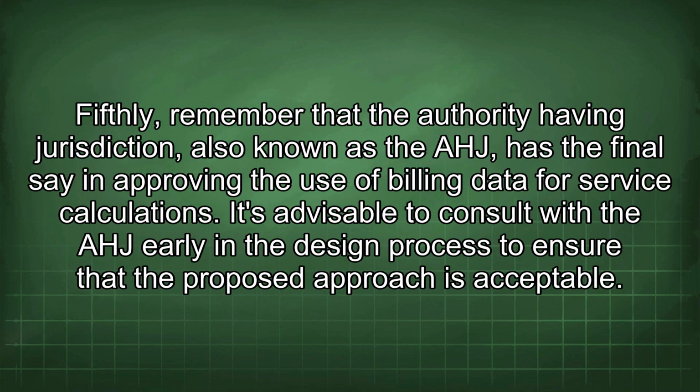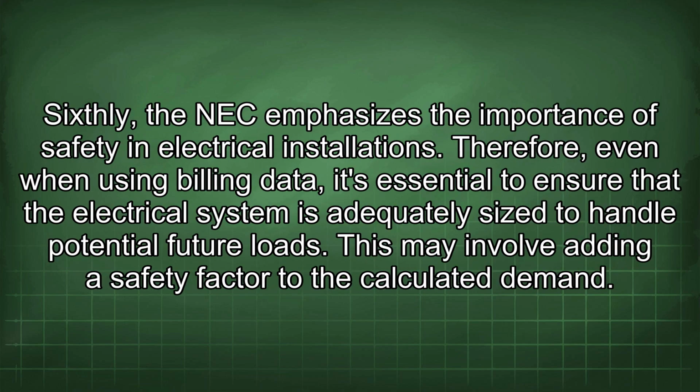Fifthly, remember that the authority having jurisdiction, also known as the AHJ, has the final say in approving the use of billing data for service calculations. It's advisable to consult with the AHJ early in the design process to ensure that the proposed approach is acceptable. Sixthly, the NEC emphasizes the importance of safety in electrical installations. Therefore, even when using billing data, it's essential to ensure that the electrical system is adequately sized to handle potential future loads. This may involve adding a safety factor to the calculated demand.